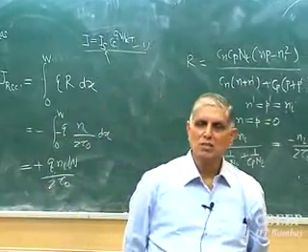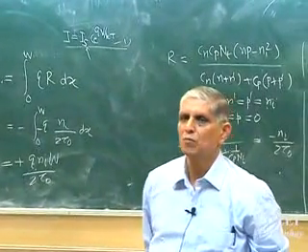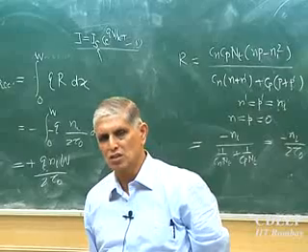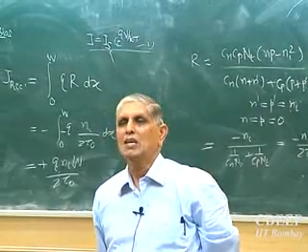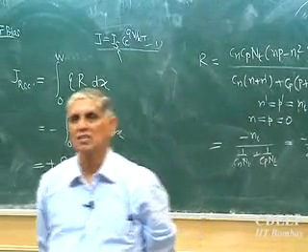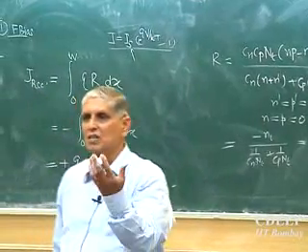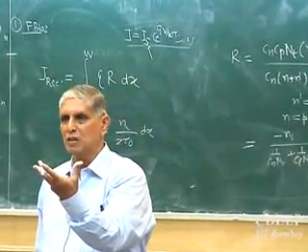So does it look constant to you? Q Ni W by 2τ0, does it look constant or is it not a constant quantity? W is a function of what? Reverse bias. The larger the reverse bias, the larger the depletion width.